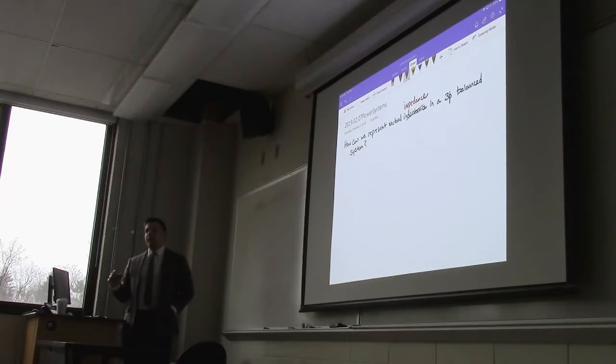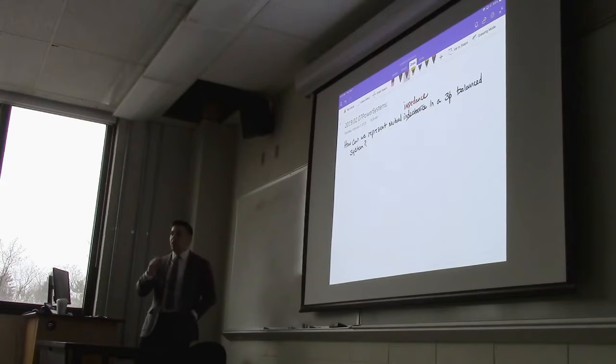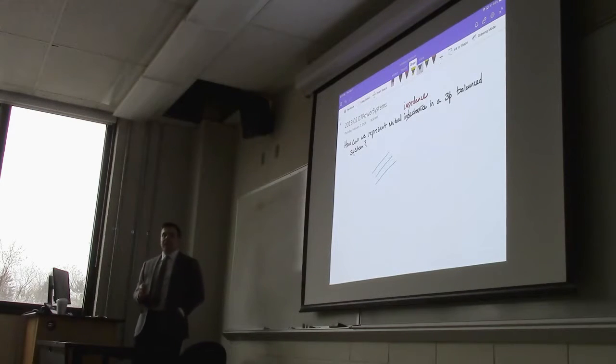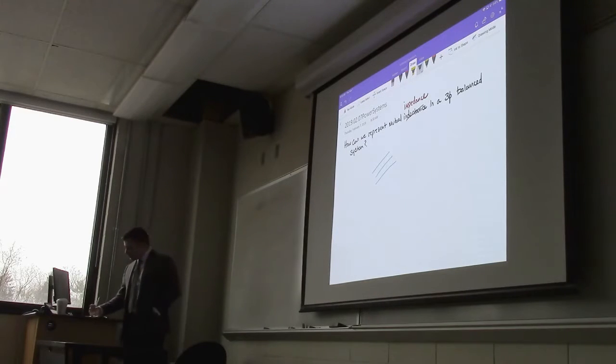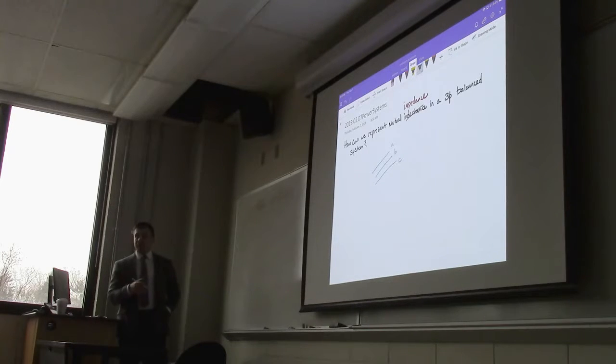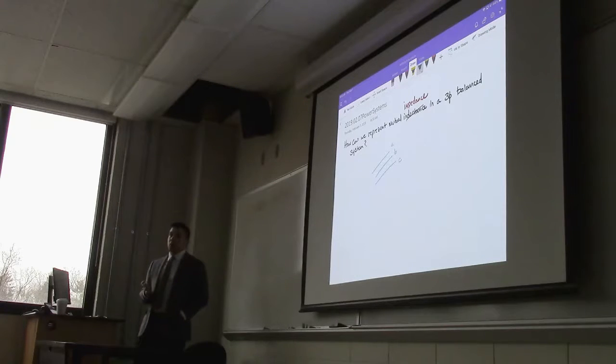So one way that we can handle the mutual inductance or the mutual impedance is proper spacing of the transmission lines. I'm not going to go into too much detail, but there's something we call transposition of the lines. If you think about three lines like this, A, B, C, the mutual inductance experienced by B, let's say B is the middle one, is going to be more than the mutual inductance experienced by C or A because of the spacing of those lines. So there are two different ways that we can address that.